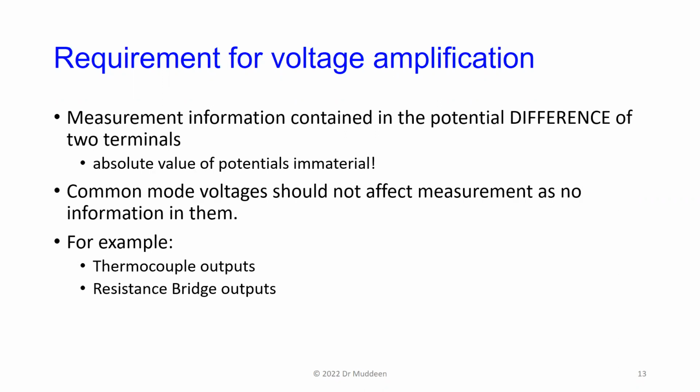If, when you go into the lab, you take a scope probe and hold it in one finger and watch it, you're going to see a 60 hertz signal coming out on the scope. It will look something like that. The amplitude could vary depending on how moist your skin is and which part of the room it is. But next time you go into the lab, just hold the scope probe, set it on maybe 1 volt per division, with the time base set to let you read the frequency, and you will notice that you have this 60 hertz.